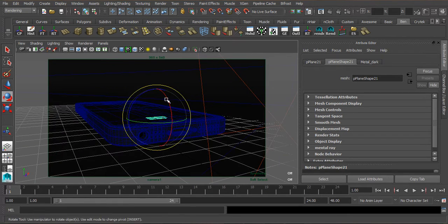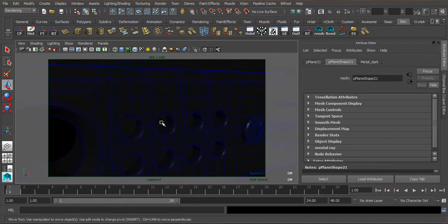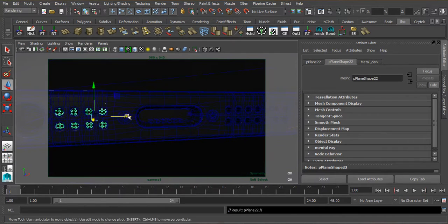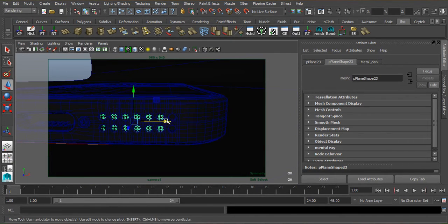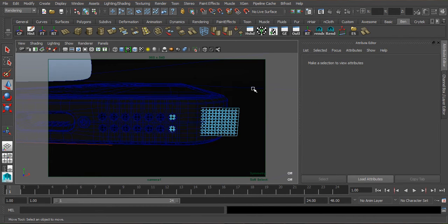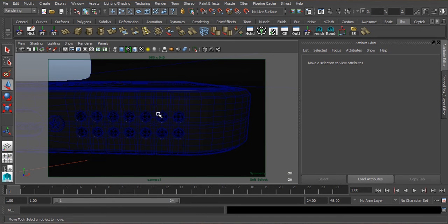And I'm also going to duplicate that and maybe just sling it in behind the small speaker holes at the bottom here as well. I might need to duplicate this one. These are a bit wider because there's no headphone jack over here. I'll go to face and trim off all of that and just hit delete. And so that's nice and trimmed off now.